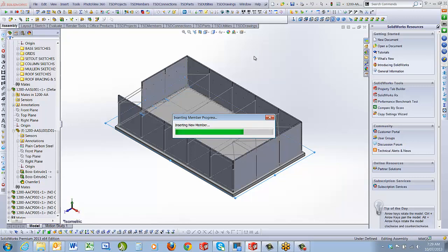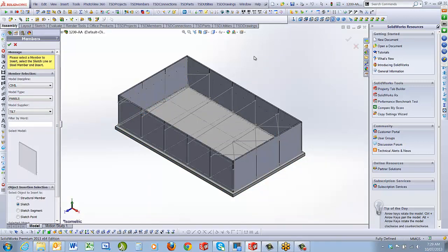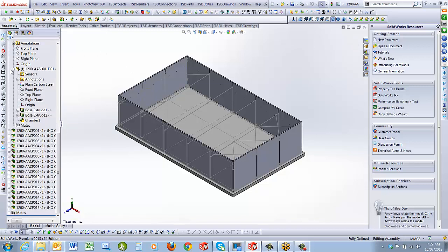As you know, when you do steel detailing and concrete panel detailing, in some instances you might think you've got the same panel, and then all of a sudden someone comes along and changes it, and you end up with a different panel. You can, however, duplicate your panels if you have the same panel. I'd probably recommend doing that at the end because then you can see it. You can go, okay, that panel's exactly the same as that. So you remove one panel from the system and then just duplicate it.